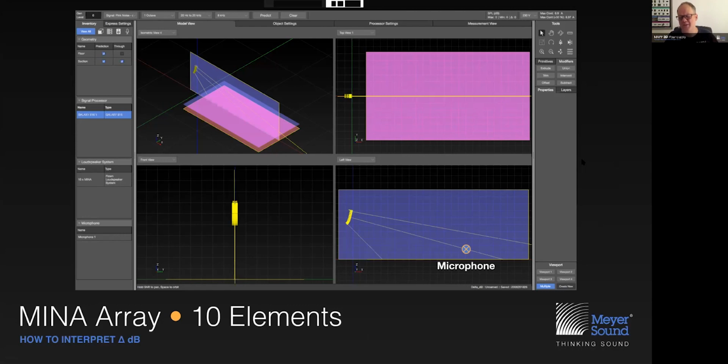I don't like flat because flat is open to interpretation. You could have a single slope and you would find people that would call it flat. So I prefer equal amplitude. As in, if I have 1 volt at 100 hertz, then in a flat response, it is expected to produce the same amount of SPL as the same 1 volt at 1 kilohertz or the same 1 volt at 10 kilohertz. I think equal amplitude is less subject to interpretation.